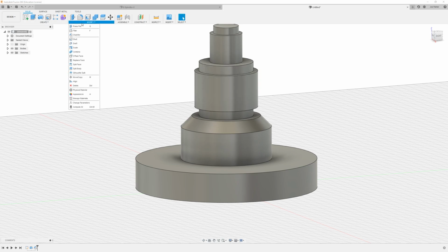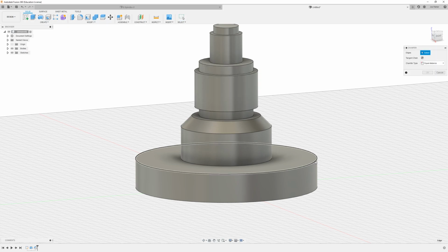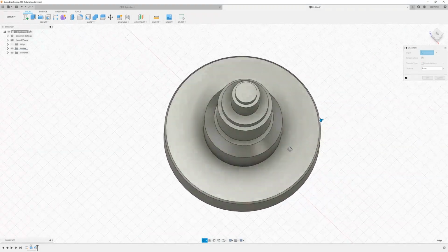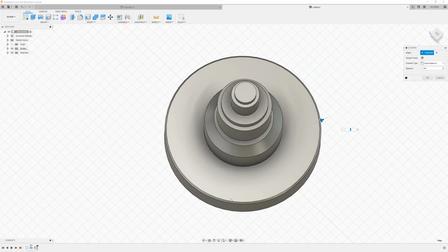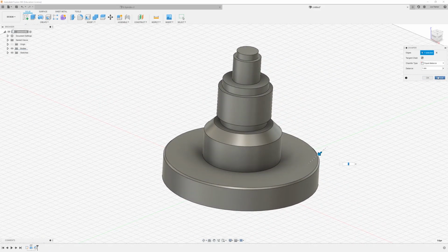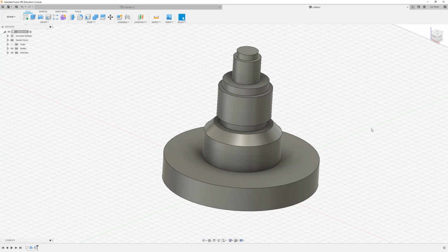And then the next chamfer feature is on this edge, and this is actually 1mm, sorry. Now, looking at my engineering drawing, I think probably what I want to do here is create the cutouts on each edge of this base plate before I place this chamfer feature. So I'm actually not going to press OK to create this feature. I'm going to press Cancel, and the next thing I'm going to do is create those cutouts.